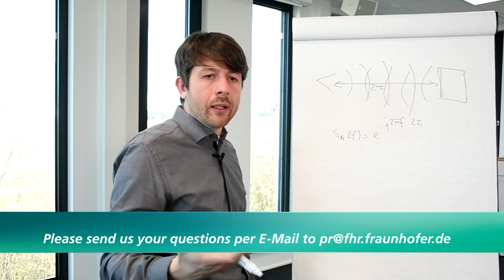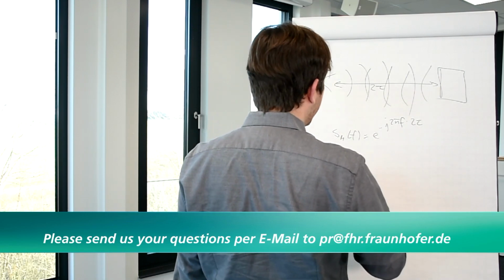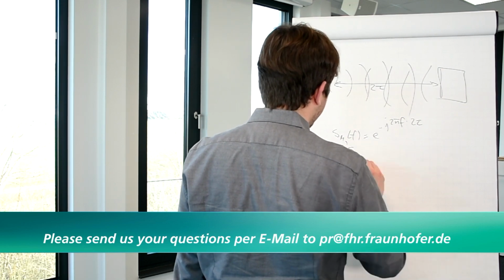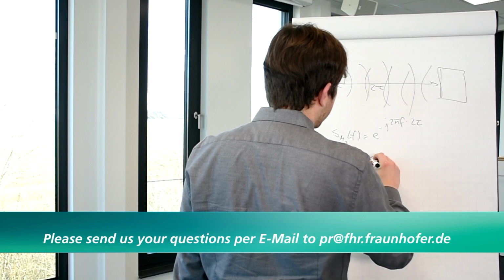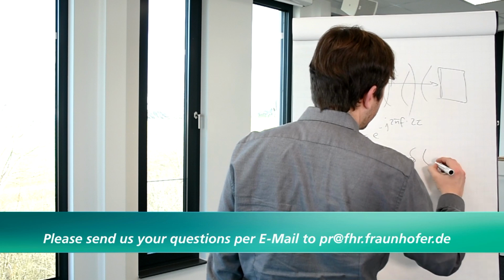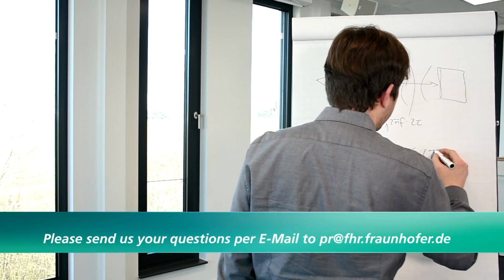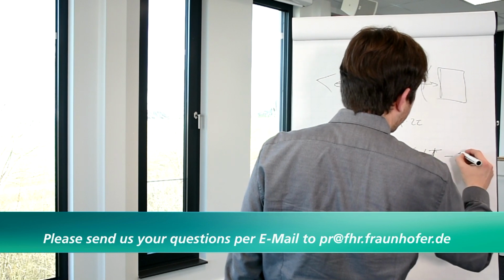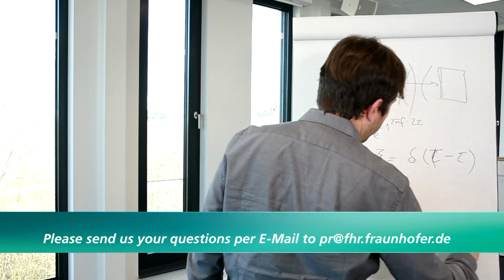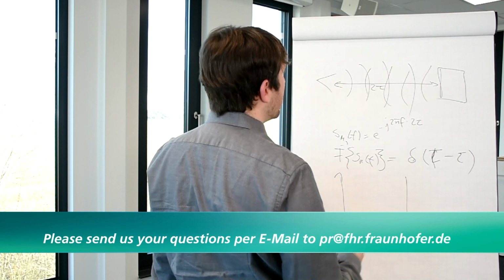And that's exactly where I can apply a Fourier transform, or an inverse Fourier transform, on the signal, which is nothing else than the Dirac delta of t minus tau. That basically means I get a spectrum with a peak at the delay.